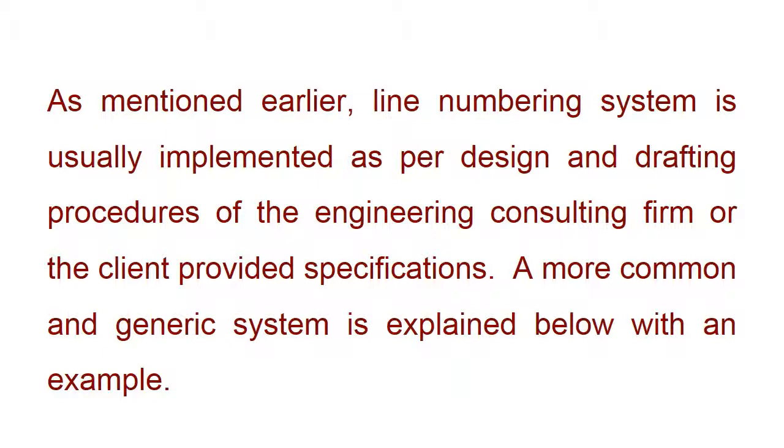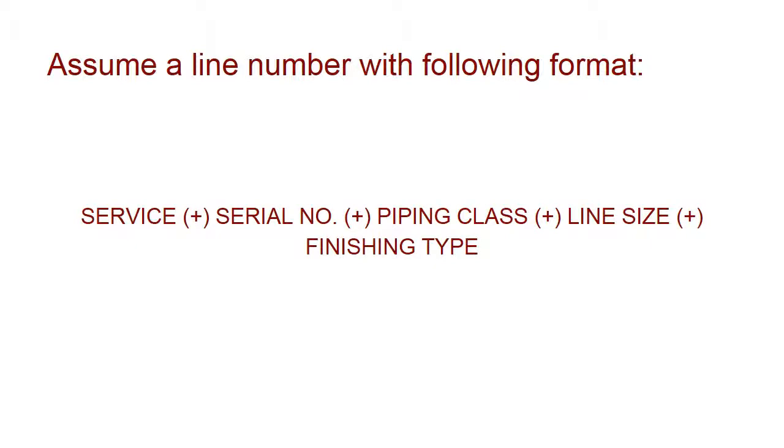A more common and generic system is explained below with an example. Assume a line number with the following format: service, serial number, piping class, line size, finishing type.